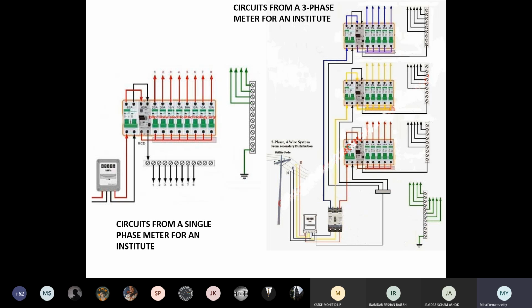I am being very deliberate here because I can't show you the diagram. I wish I could do this on a board. Similarly you will have the living room, the kitchen, some balconies, and laundry if you have that. You might have a drying balcony where you have a light there, so probably one for the light there. It depends on how your electrician has distributed the lights within, but ideally as many rooms as there are, that many MCBs there are.